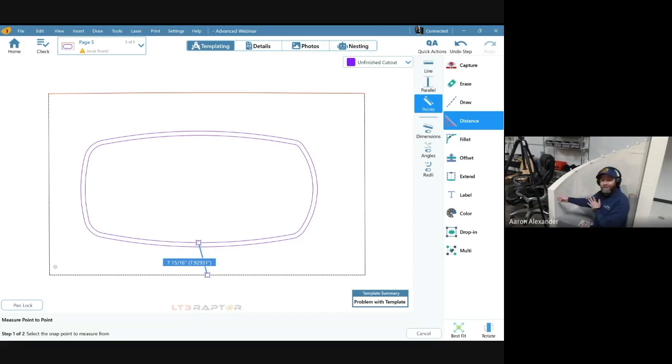If you get to the end here and you got an X floating out in space, that means you didn't calculate that with your spacing out right. So you might want to back up and shoot 2 points in that area there to get you that last arc there. Okay, that's what I mean by that. So that's using arc mode to scribe. We talked about arc mode for a tub deck. Now, in a situation like this, if you were scribing this wall to butt a countertop up against, we want to cut the back edge of our countertop to match whatever the carpenter gave us there. By scribing it like that, we're going to get that. We can fabricate that on the saw, water jet, router, whatever we're going to cut that with.